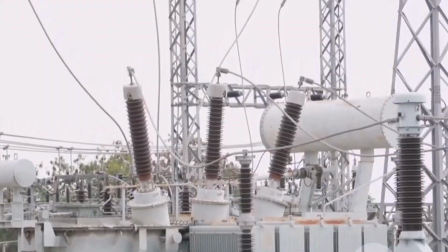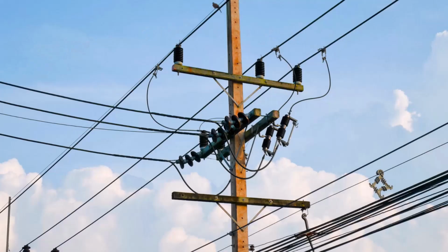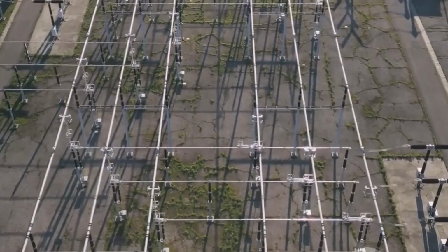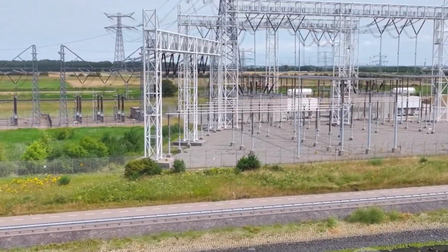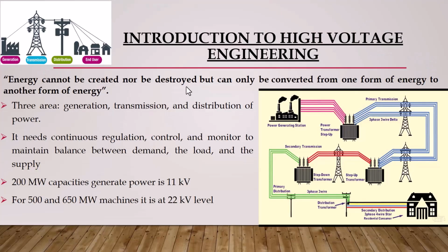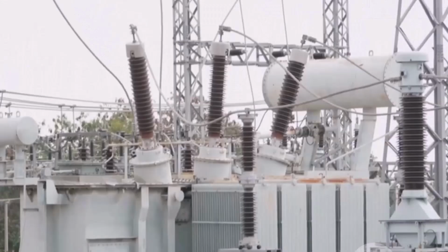And here's a point I want to emphasize. Higher power doesn't necessarily mean higher generation voltage, but rather, as power level increases, we choose generation voltages that balance equipment size, insulation requirements, and efficiency.